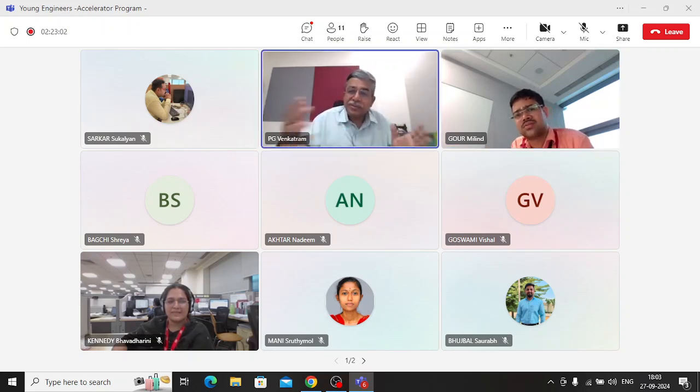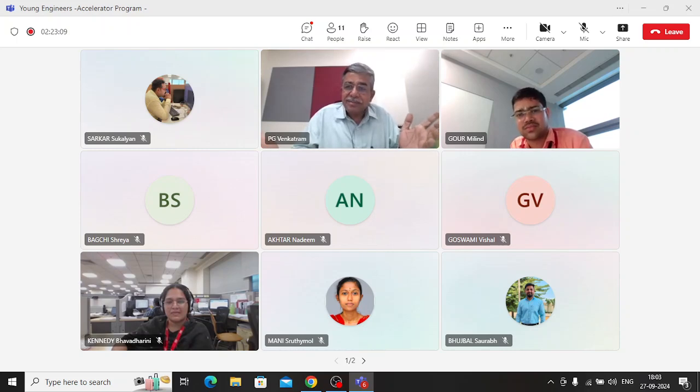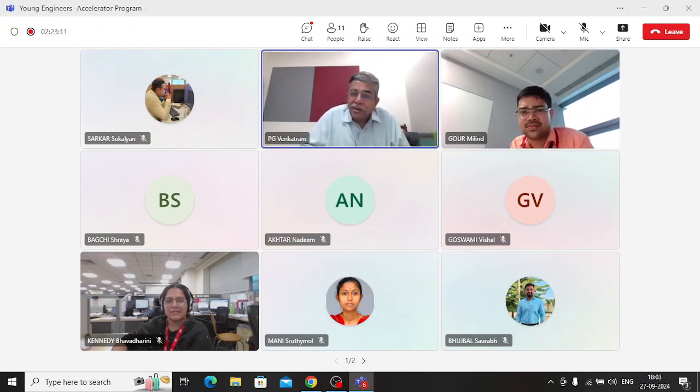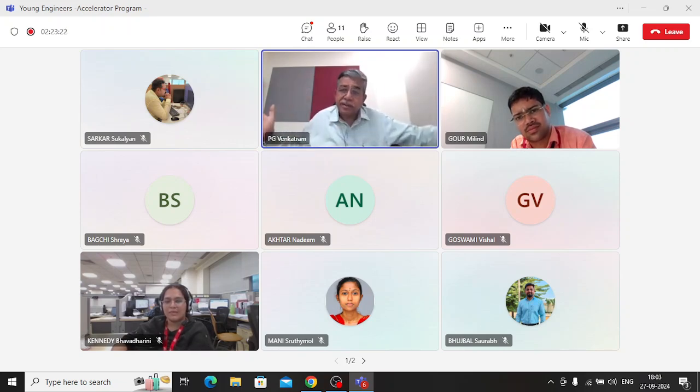So when you talk about a transverse deck, your typical deck will be what? 11 meters. Well, the widest deck may be 20 meters. So it is practically not economical to do pre-stress concrete. It will not be effective. So we tend to do transverse in RCC and longitudinal in pre-stress, especially for the longer spans, because longer spans are uneconomical in RCC.